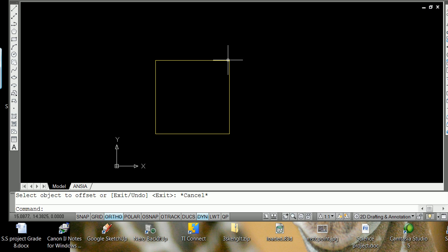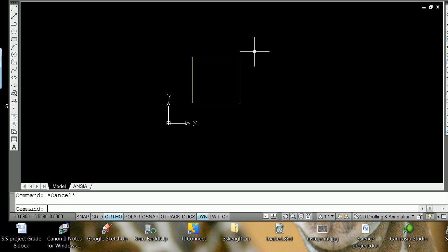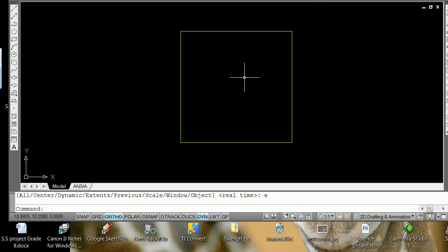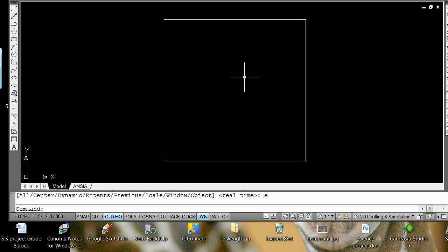I now have my box drafted, and you notice it is in four different pieces. I can do a double click in the middle mouse, escape, escape, escape, Z space, E space, and I have this general sense. In this drawing, we wanted to set up a center line, keep it in the middle of the box, so once again, I'm going to turn my dynamic off.